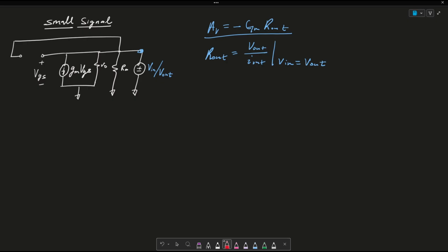In order to solve for Rout, I'm going to label this Iout. I'm going to label the current that it splits here as IN, the current that flows in here as capital ID, the current that goes here as IO1, and the one that goes in here as IO2. I hope that makes sense. What we can obviously say is that IN is equated to 0 because there's an open circuit here, so no current can flow through that. Let me call this equation number 1.